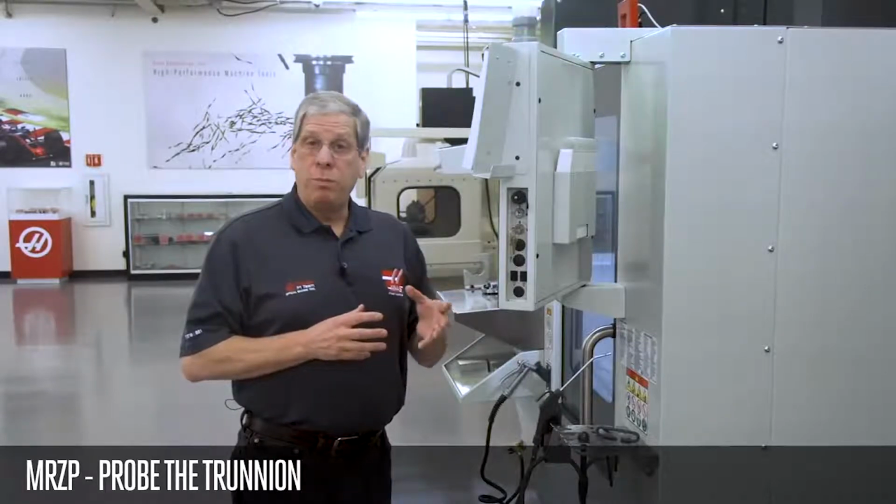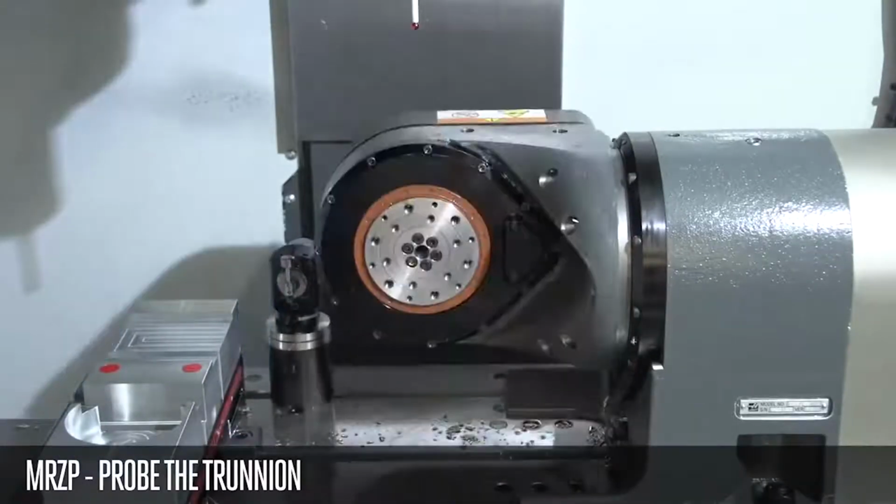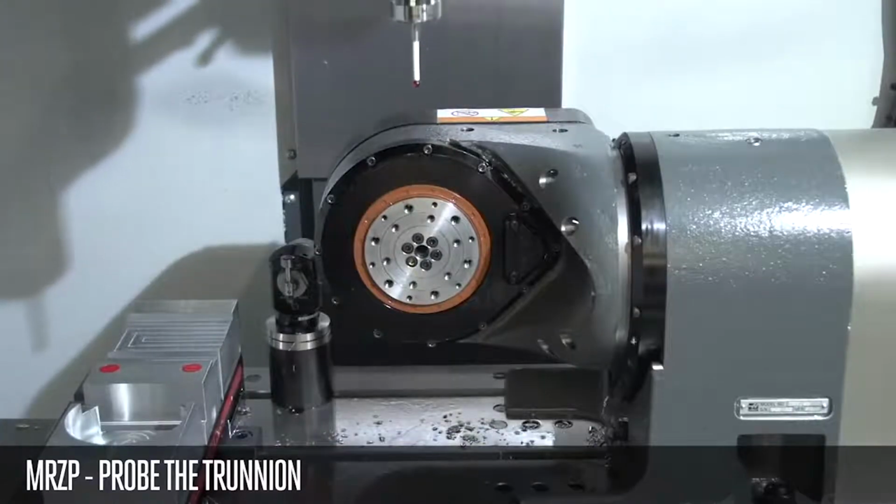The cycle will probe the center bore of the rotary and get the X and Y coordinates for the C axis. It'll probe the platter to find its location in Z, and then retract and rotate the tilt axis to 90 and minus 90 degrees to find the center of X or Y.